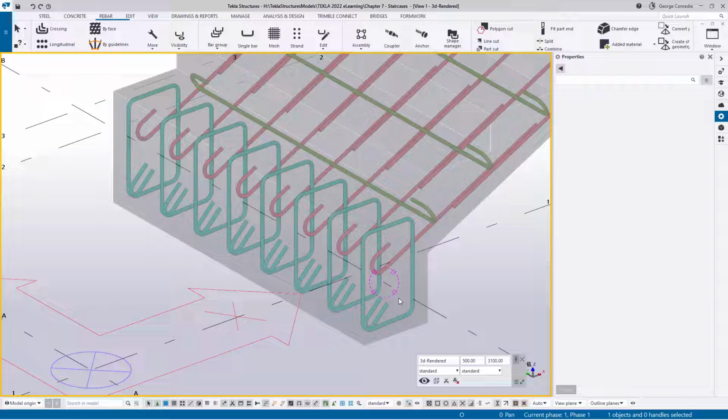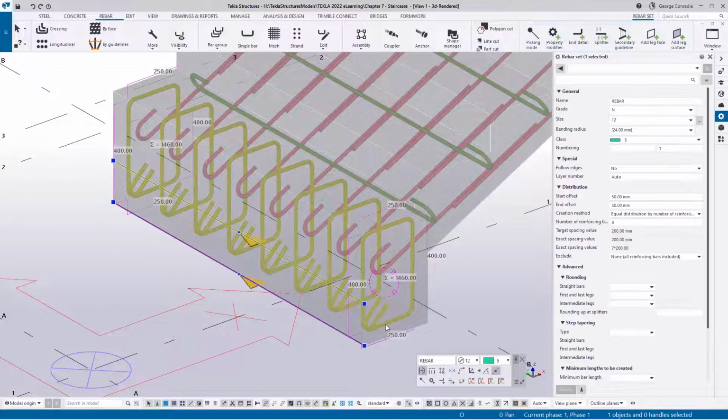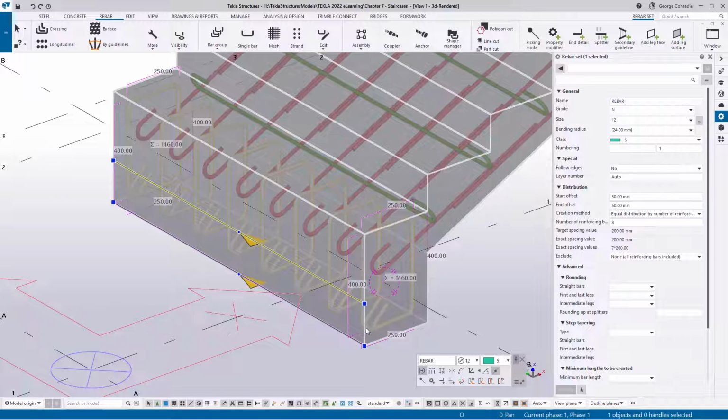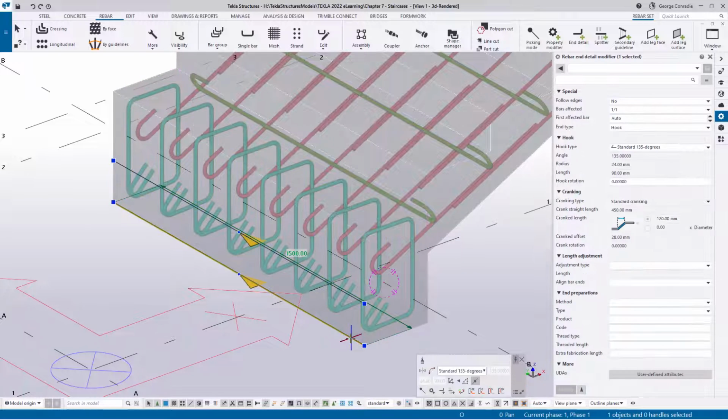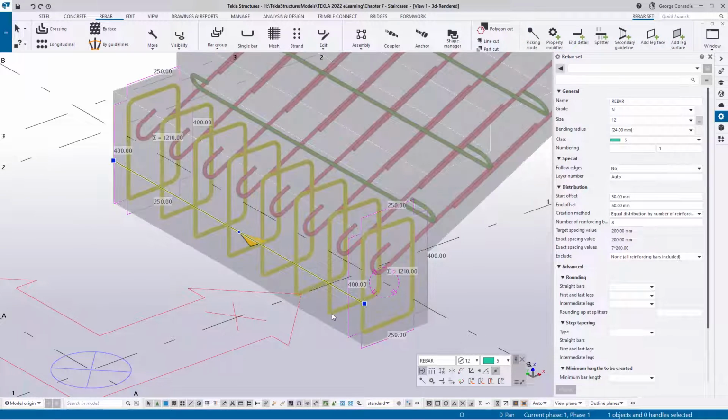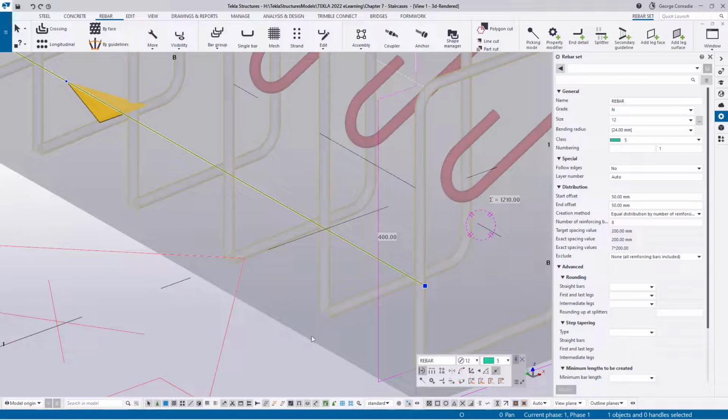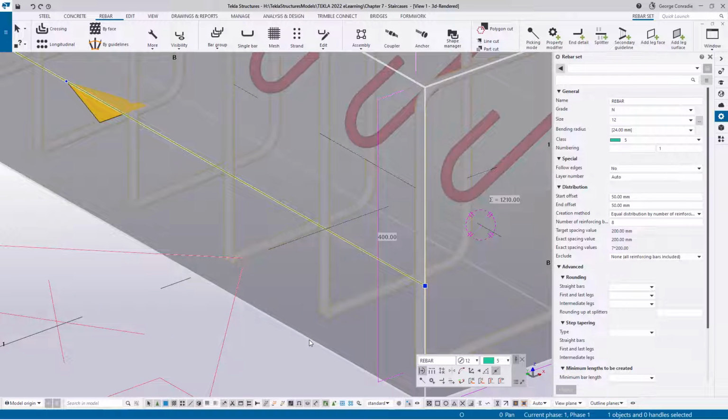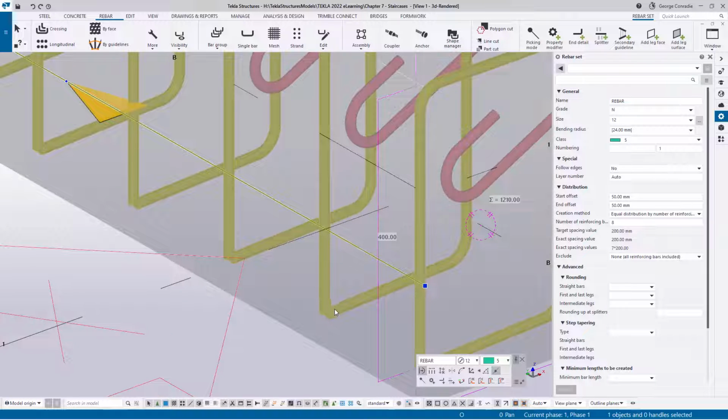Now, just a note, I think I've said it in previous videos before, but just for those that didn't watch those, if you have a situation where your ligatures start and end at that point, this concrete edge is exactly the midpoint between the two. So if you put an end modifier there, it will put an end modifier on both points.